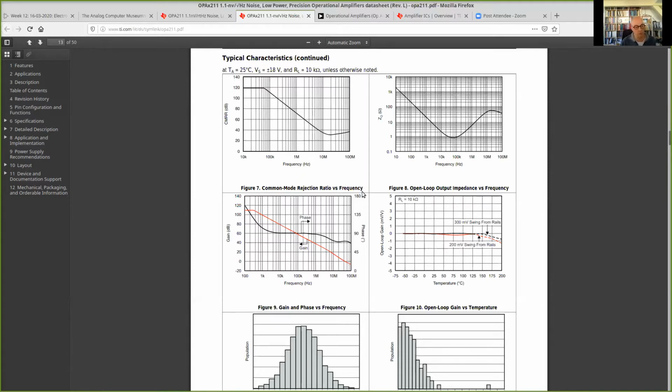you have to really always study what they mean with these numbers, because of course for DC there's no phase shift, so it should be 0. But if you measure the inverting input, it will be 180 degrees, of course. So we go from 0 to -90 degrees.